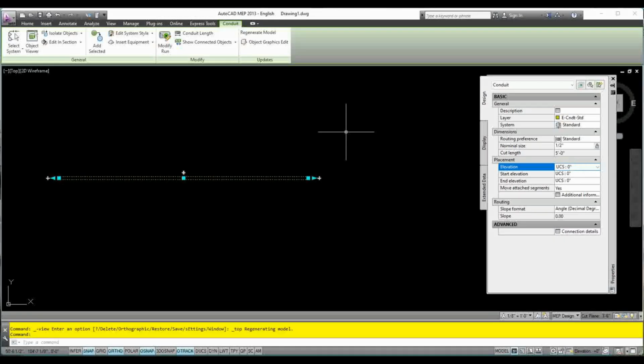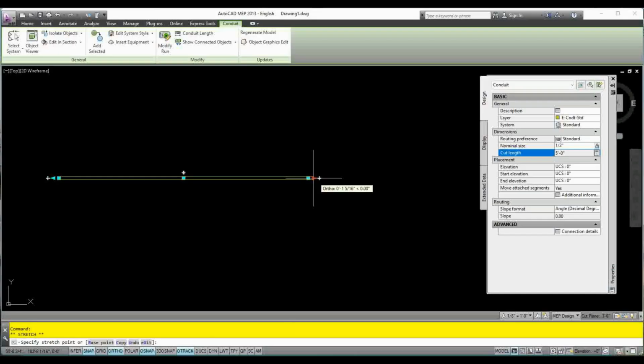Everybody, if you haven't, click on this piece of pipe, highlight it, and you'll notice it says 5 feet. Well, let's get out our pipe stretcher. Click on that arrow. It did say lengthen, right? So you pull it out, type in 2 feet, on your keyboard hit enter. What happened? I guess I didn't type in 2 feet. Let me do that. 2 feet, enter.